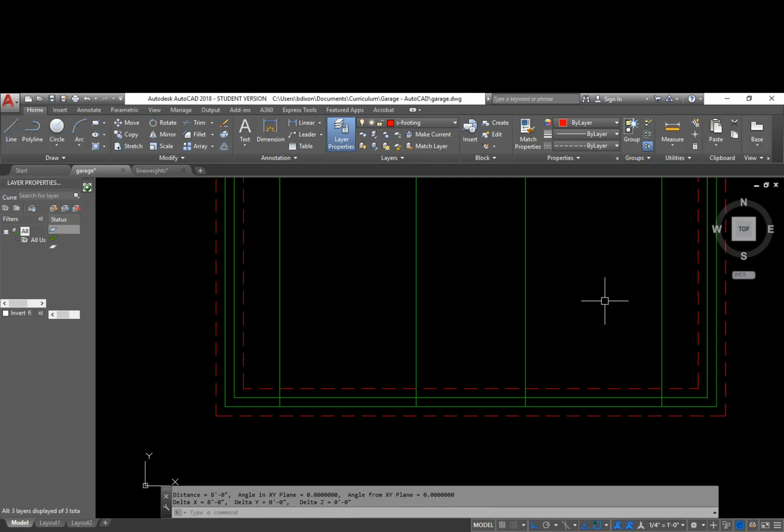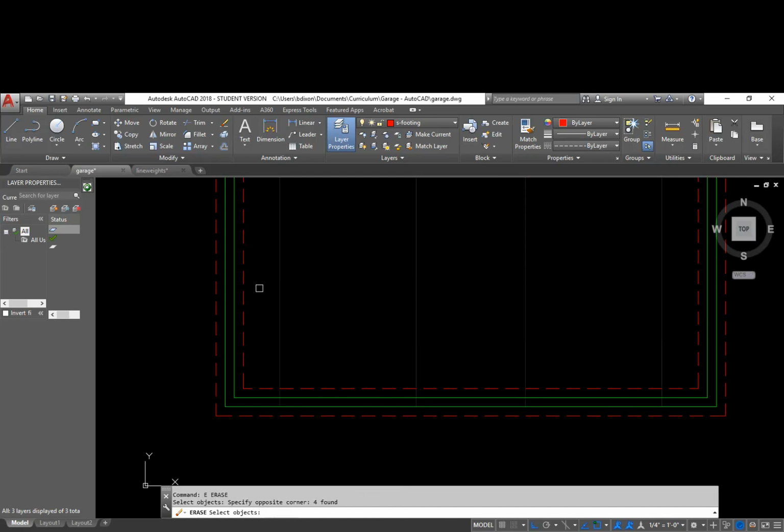If I divide that by 3, I'm going to get 5 feet 4 inches. So 5 feet 4, it's odd feet, and it ends in 4 inches, so it follows our modular dimension rules. So that would be an easy one to use to give nice even dimensions the whole way throughout here.